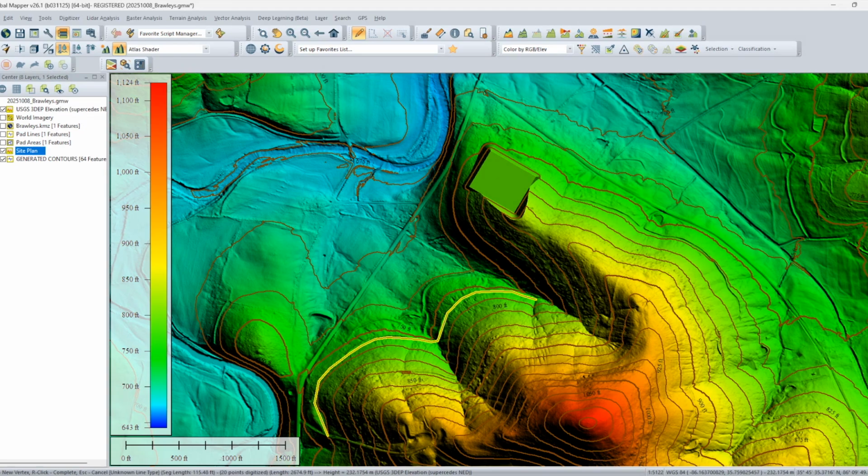By picking the alignment close to same elevation, I'm reducing the work that the code will process to a minimum. If I don't do this, the values can go out of whack during processing the data. This step is important, that you start with close to a realistic road alignment. Our employer might have deep pockets, but that doesn't mean we are not cost conscious and safe in building this road. I am almost finished with the first pass on the alignment. Don't worry about these sharp turns and tight curvatures, because the code will adjust the radius in accordance with your input, which will have speed, length of the vehicle, and vertical grade.